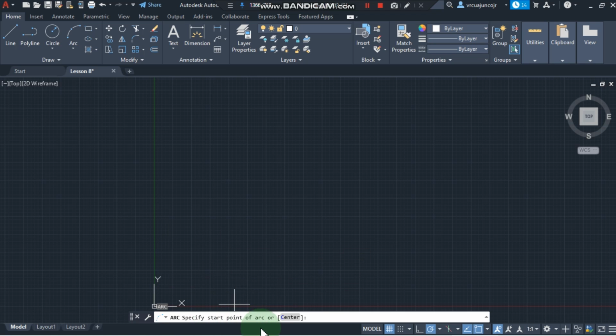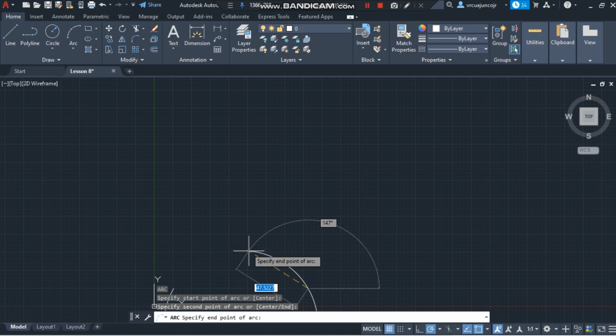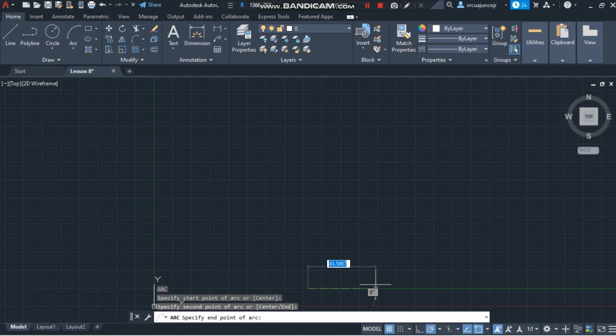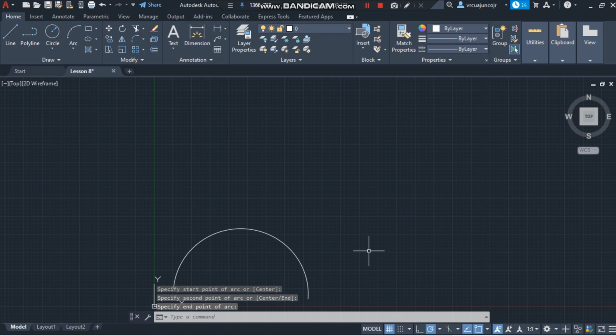So we have A for arc. So specify the start point of the arc. So let's have it from here. Then the second point of the arc, let's say from here. And where do we want it? So that's an arc. From this point to that point.